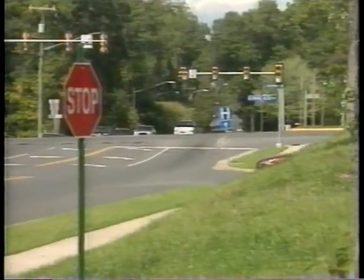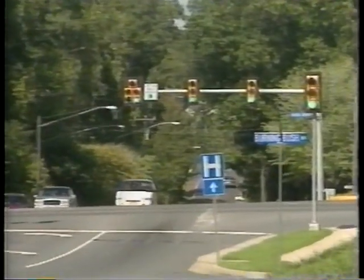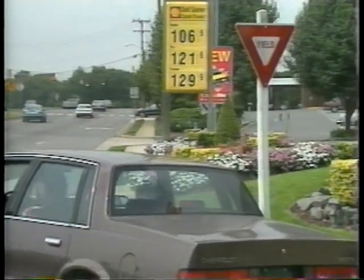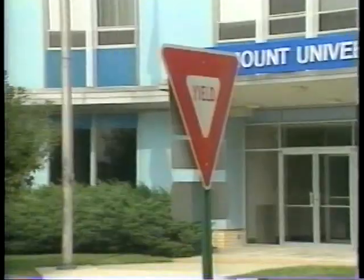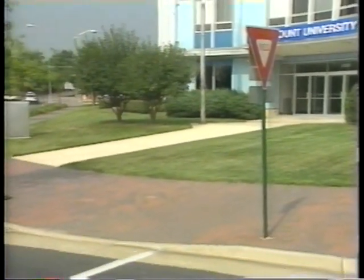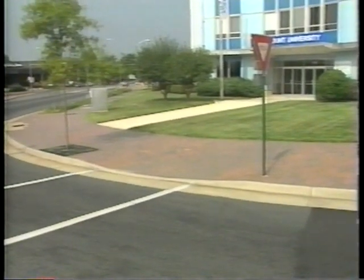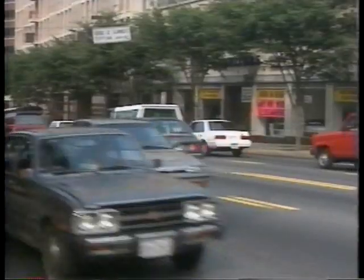Stop signs are used for unsignalized intersections in a signalized area. A yield sign should be put where the vehicle is to stop, if necessary, to yield the right of way. If there is a marked crosswalk, these signs should be put 1.2 meters in advance of the crosswalk line, nearest the approaching traffic. A critical mid-block sign is the speed limit sign.